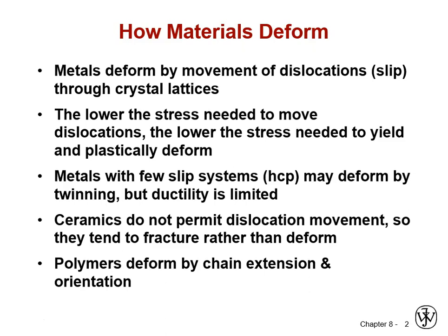We did discuss that dislocations move easier on certain crystallographic planes than others, namely close-packed planes are ones upon which dislocations like to move, and close-packed directions are the directions in which dislocations like to move. So if you have your applied stress on your crystal or your grain, if you have a polycrystalline material, aligned to push the dislocations on those close-packed planes, it won't take as much force to move them, or as much stress, force per unit area on the grain.